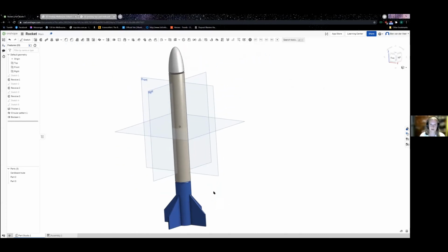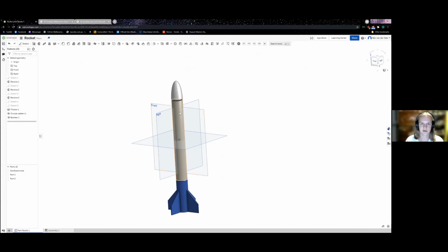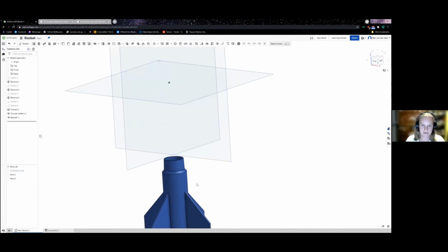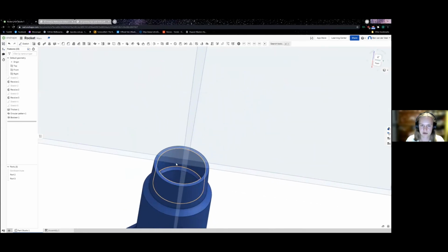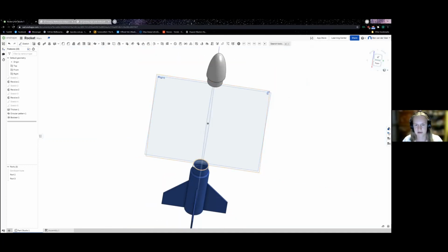And so this is a rocket that, provided you have the right size cardboard tube, would be able to be printed off. Just these two parts could be printed off at the Uni 3D printer, and it could be ready to fly. You'd just super glue, similar to what I have done on the inside here. I have super glued and taped over it while it was drying, the inside of the parachute line to the inside of my nose cone. The same can be done for this lower fin can as well. And this is a quite acceptable design.